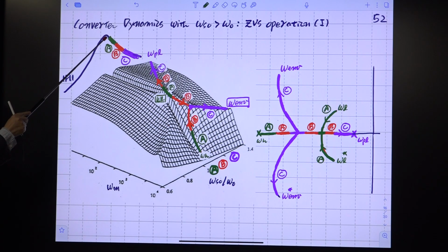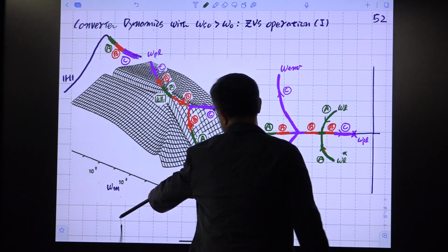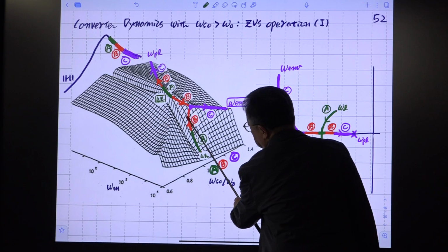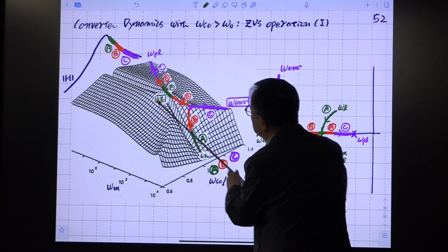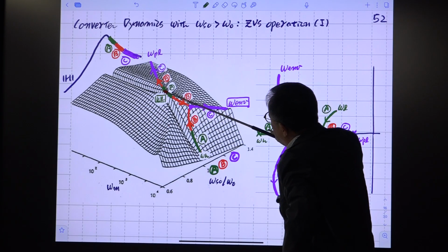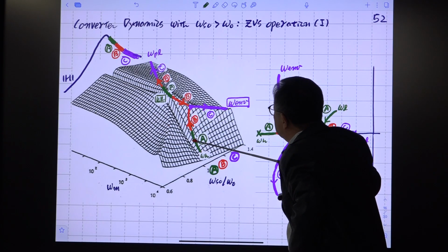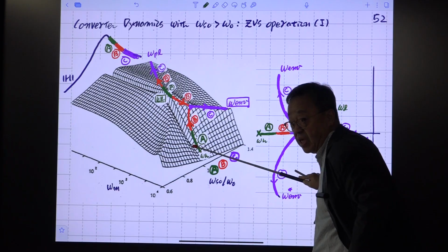And you increase your switching frequency slightly higher than this tank resonant frequency. You are in this A area. So increase your switching frequency a little bit, then it is this A area. Okay? So this area generates one low frequency double pole at this low frequency, and one single pole, single dual pole at high frequency.